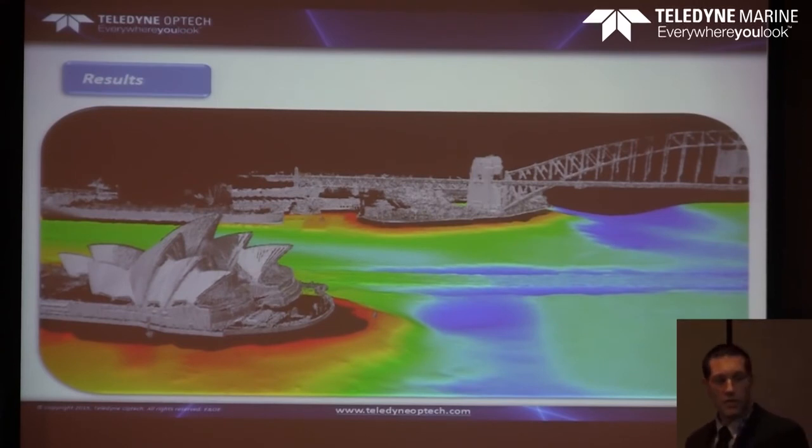So what you can do, there are different ways to do it. You can play with the tide, so whenever there's low tide or high tide, you can survey the missing points, or you can actually tilt the sensor head, the multi-beam, by 30 degrees, and you get this data set. And this is what we did in the next slide.